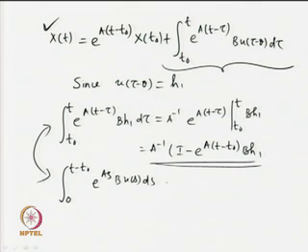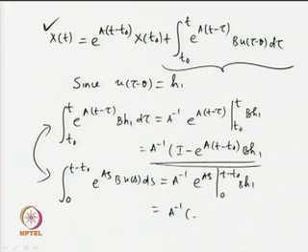Now, the bottom one can also be solved and found as A inverse e to the power A s with the limits 0 to t minus t0, and you have u(s) equal to h1. So, B h1, and that will give you A inverse [e to the power A(t minus t0) minus I] B h1. So, there is a difference in sign only.